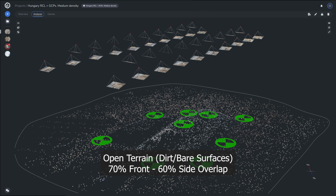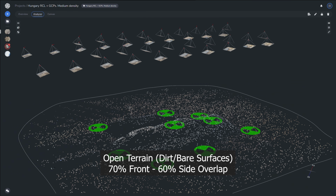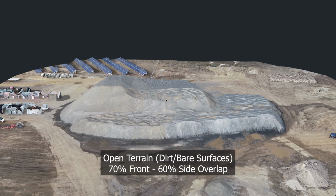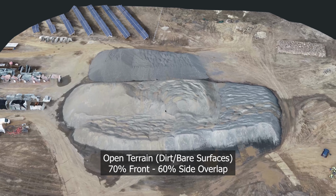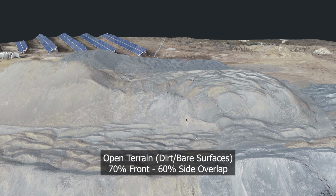For open ground, such as dirt or bare surfaces, 70 to 60% overlap, meaning 70% front overlap and 60% side overlap, is typically sufficient. You could even go as low as 60-60 for faster coverage.